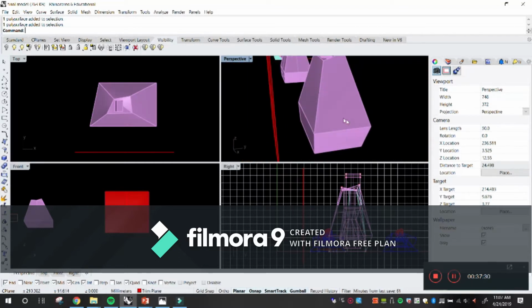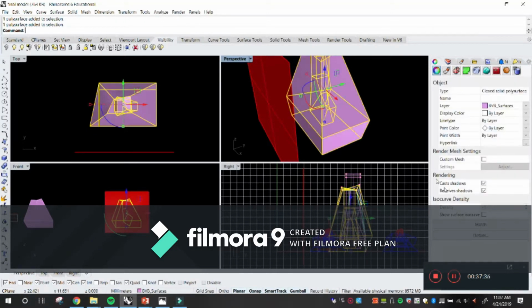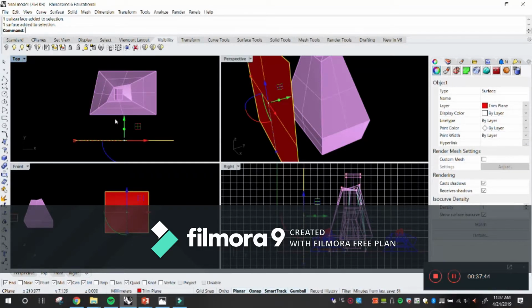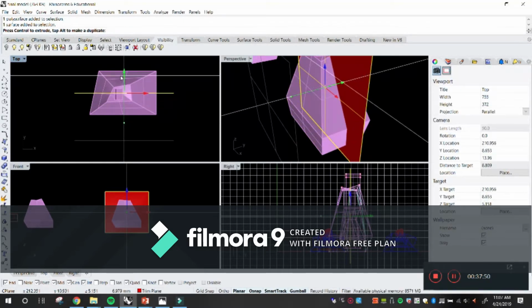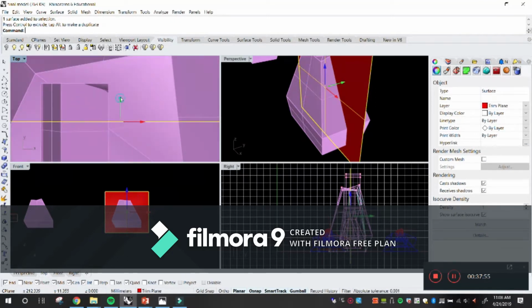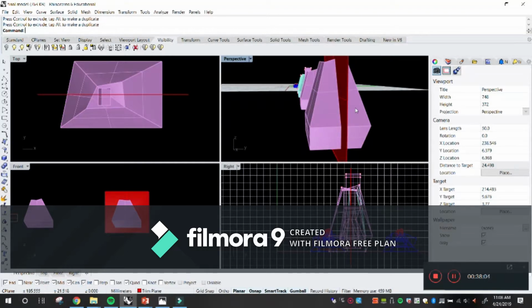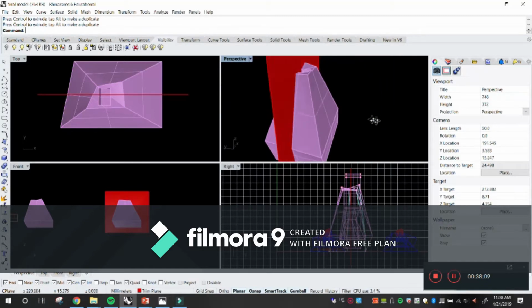Now I point that out because I'm actually going to use it. So I go back, select the object, and show them. Kind of like what was mentioned, the axis of the object. I'm going to use that as a guide, and place the plane somewhat centered on that line. I'm using it as a reference, because that will be more or less technically the half point or the center point of the object. That's it. So the plane is now intersecting the objects that I want to split.